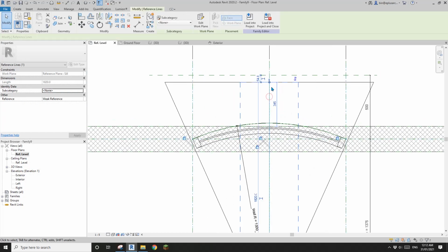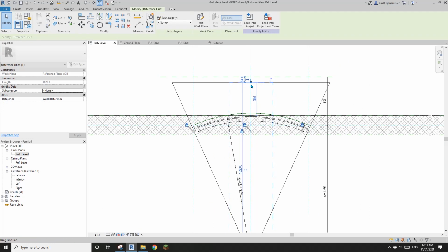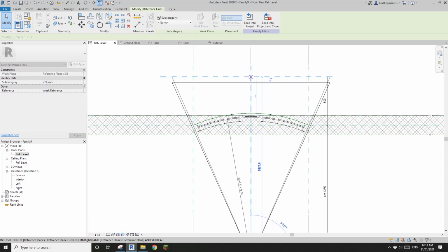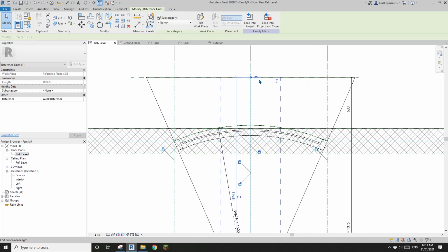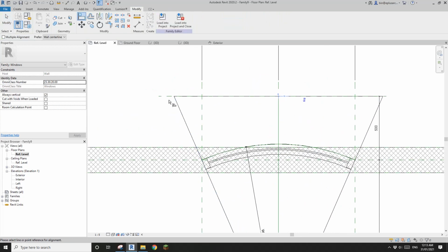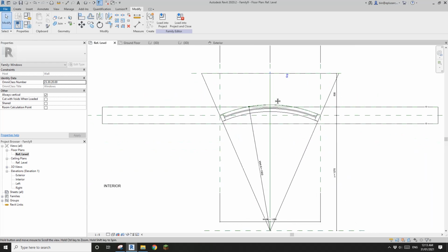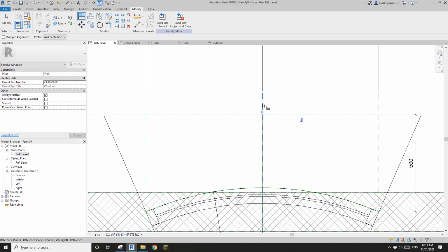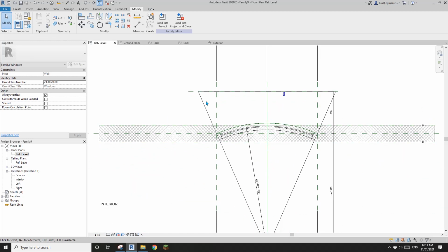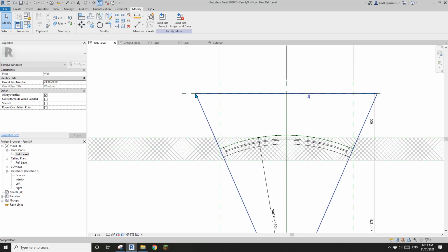This is a path, we just need to drag this path to the reference plane and lock it. How do I lock it? Maybe I'll just use a line to lock this. Tab, click, lock. Okay, there's a little 0 here. Maybe I'll just also lock it. Okay, all good.